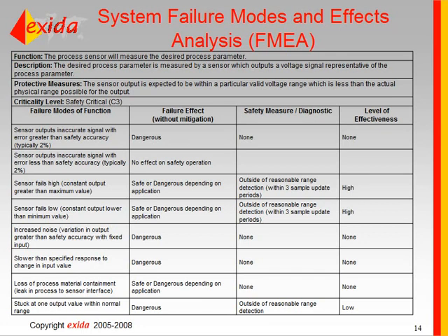So it can be high, medium, or low, and that roughly translates into a high effective diagnostic should detect 99% or more of all problems. Medium effectiveness is 90%, and low effectiveness is 60%. So what do you do with this analysis when you're done?